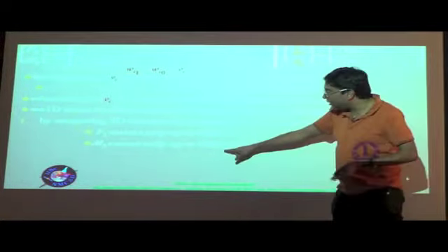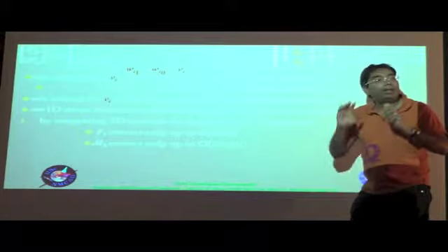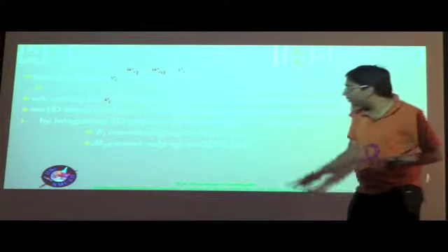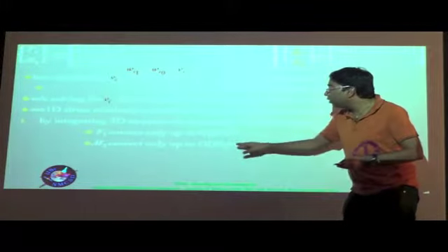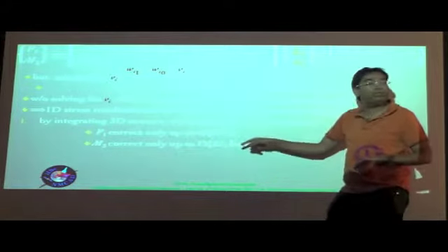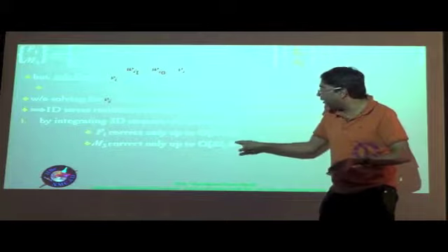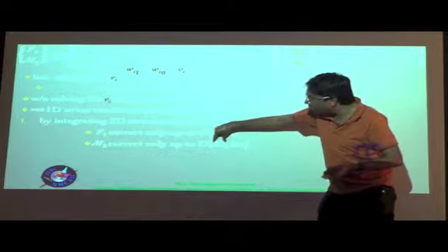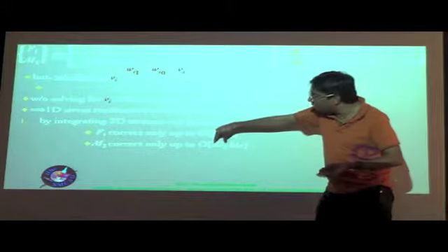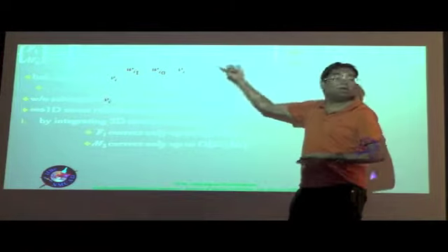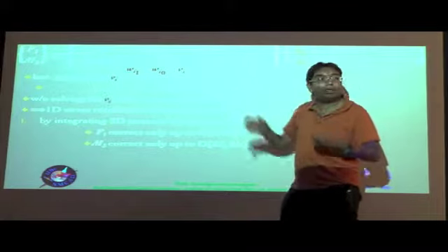If you had determined it in that way, once again you would have the correction asymptotically correct only up to the classical level, that is basically your EI3 times epsilon hat by a, because basically it is a curvature, so it should have that dimension. So that 1 by a aspect is coming into it, that is basically the curvature that the bending stiffness multiplies. In other words, your bending stiffness is correct only up to the classical level and does not involve these higher order terms accurately to the extent that it is necessary.